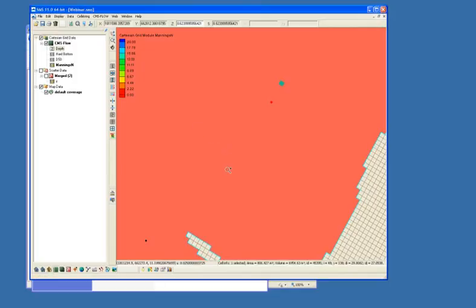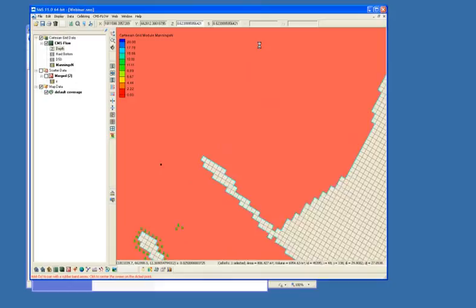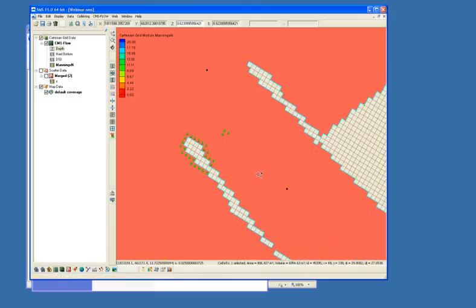If you wanted to go in for a certain area and increase the friction for whatever reason, maybe it's vegetation or flow through bridge pilings or things like that, you could, just like we did earlier, select those cells and change this S value at the top.